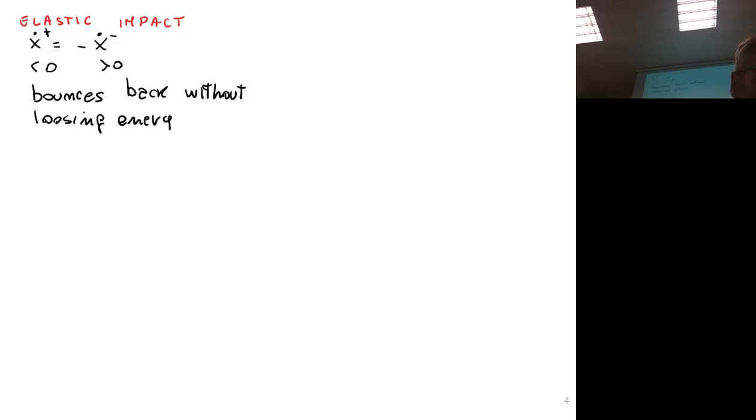So in this case, it bounces back without losing energy. But in the case of inelastic impact, the velocity after impact is opposite with respect to the velocity before the impact, x dot minus, but it's a fraction of that. So we have energy loss.